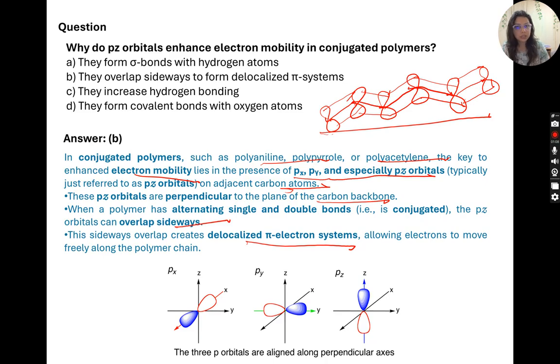So this cannot directly impact thermal conductivity, but this kind of arrangement, from the crystalline structure, can increase phonon transfer or decrease phonon scattering, so ultimately it can increase thermal conductivity also. In structures like polyaniline and polypyrrole, thermal conductivity is higher compared to others because of their structure.